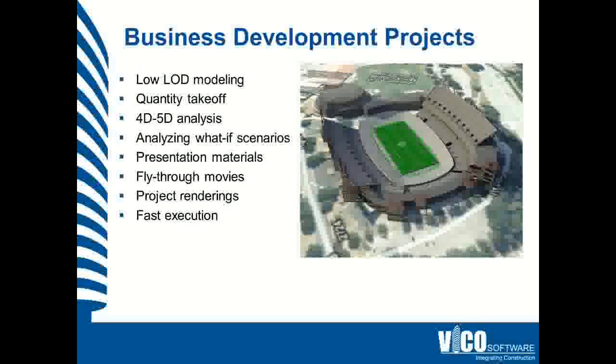So as I mentioned, the business development projects, we use this term when we are involved in a bidding phase, and we have really just design development or schematic design documents, but we still have to put together a building information model on one hand to show the owner the BIM capabilities that the company has, on the other hand to reduce risks and run a couple of what-if scenarios, different variations, for example, for facade or different phasing and different scheduling variations.